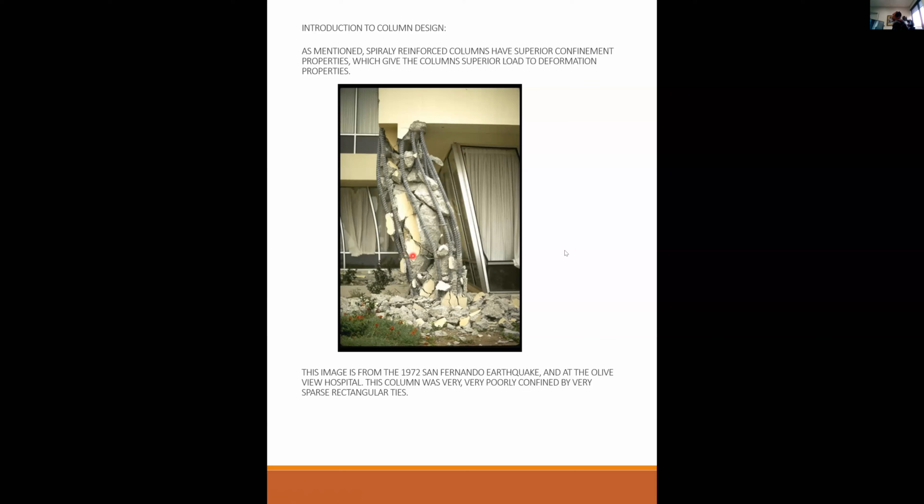Yeah, I thought there would be some type of visual cue, but I guess not in this particular case. Not for seismic. Now, if you're having a problem with a column design that is under just gravity load, that's completely different. And there are signs that you could look for distress in the column just under gravity load. That would be spalling of concrete, cracking of concrete.